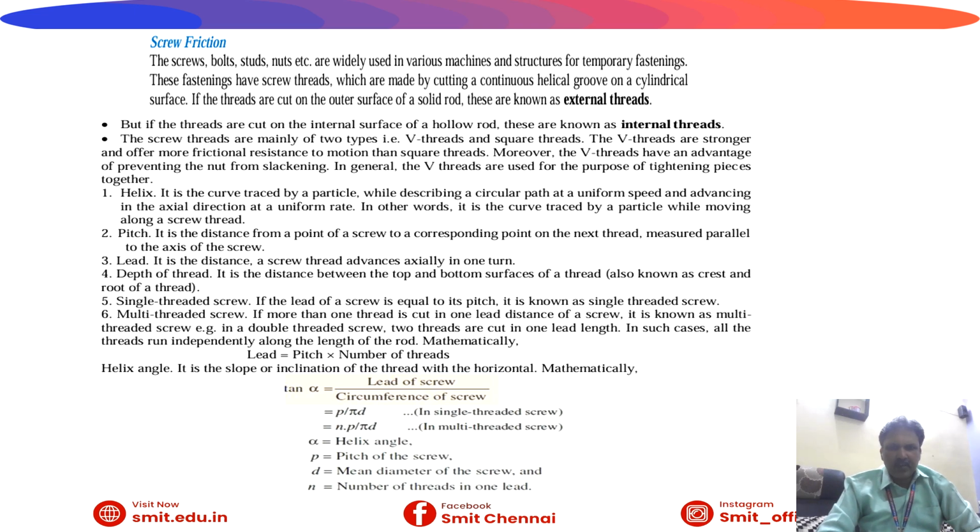Helix: it is a curve traced by a particle while describing a circular path at a uniform speed and advancing in an axial direction at a uniform rate. Pitch is the distance from a point on the screw to the corresponding point on the next thread, that is, the distance between two consecutive threads. Lead is the distance a screw thread advances axially in one turn. Depth of thread is the distance between the top and bottom surfaces of the thread, known as the crest and the root of the thread.